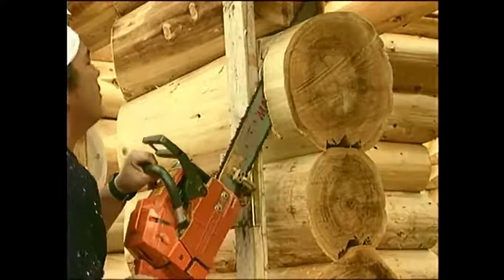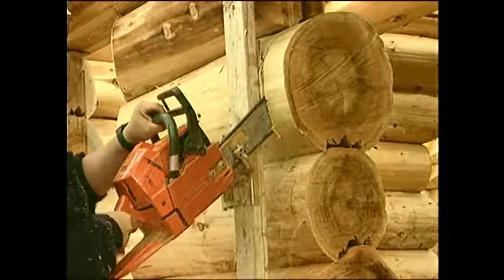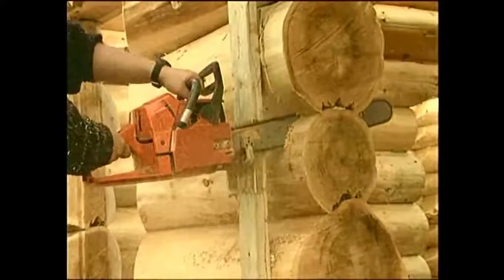Cut the sides of the opening to the final dimension. Use a saw guide or a padded saw to make the cut. Be sure that the guide plank is wedged into line with the center line of the wall so that you're getting it cut at right angles to the wall.